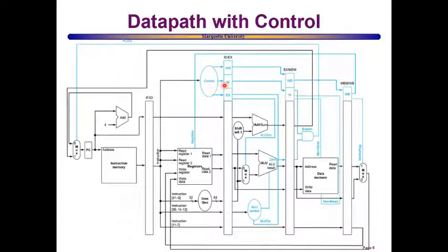The trick is to generate and then carry them through the pipeline stages together with the data. For that, the pipeline registers need to be expanded to also latch and carry over these control signals, which are each consumed at the right pipeline stage later on.